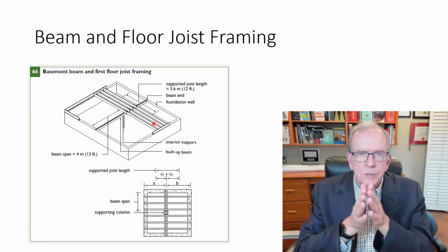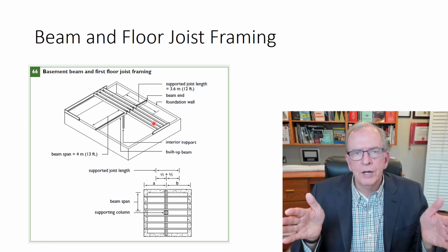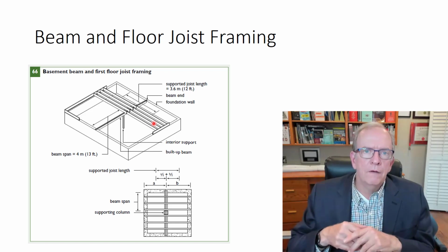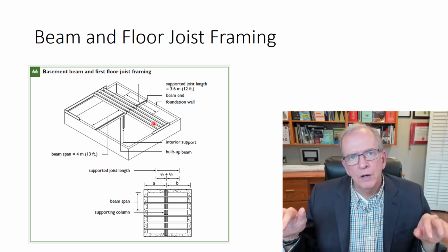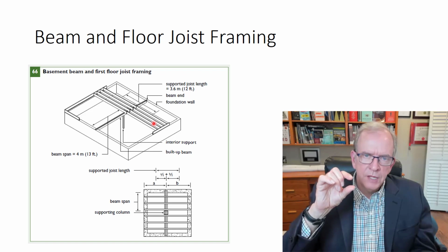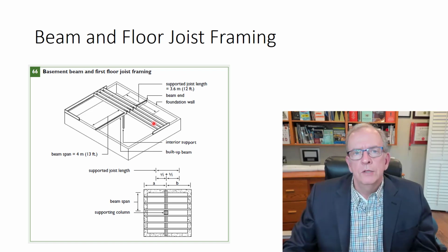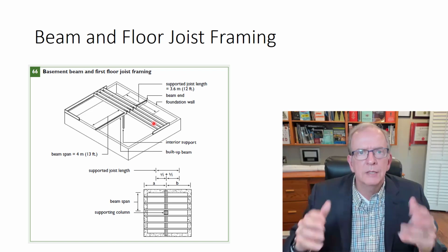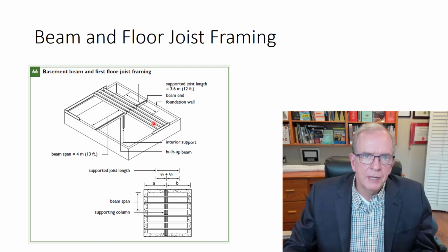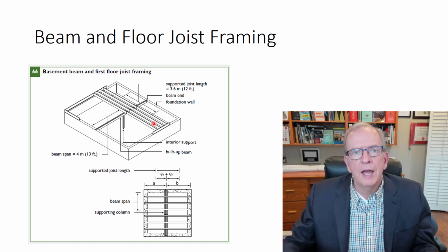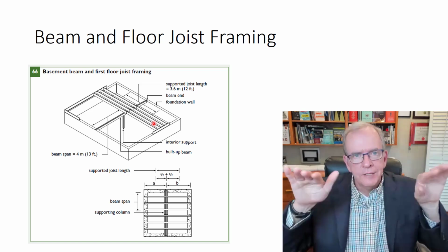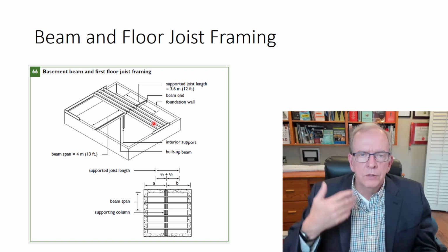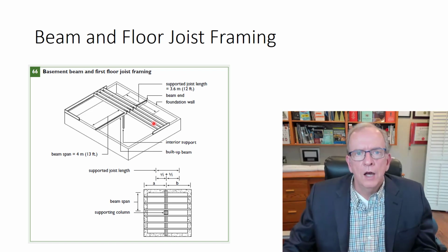So the spacing for floor joists is a direct relation to how far the joists are spanning, the type of finished material you might be putting on it, the thickness of the subfloor required for it. So it's a number of factors that go into that, from building code requirements and the design side. For example, if you're putting a ceramic tile, it'd probably be preferred to have a 12-inch spacing so you have less deflection on the joist. These kinds of things go into the design and the spacing of the joist.